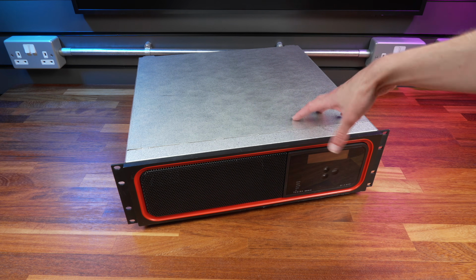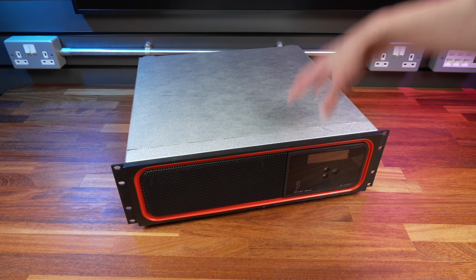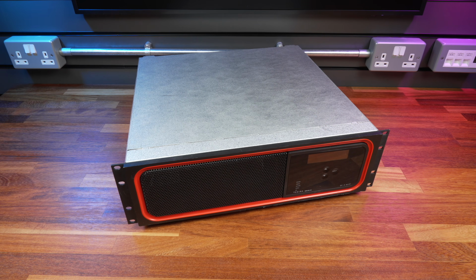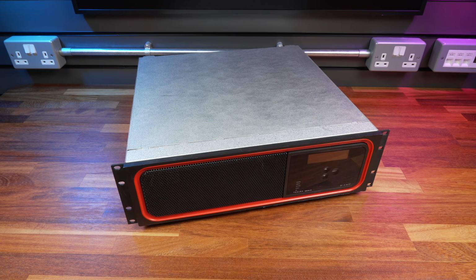And my particular machine contains a Dante card which supports up to 64 input and 64 output channels of audio. So with that connected to the network, all I need to do is route the devices from all the individual Dante devices into Tesira's Dante card and it'll just work. I don't need any sort of physical connection for each TV's audio at Tesira's end, it's just fed straight into Tesira over the network and then it comes out of Tesira direct to my amplifiers.